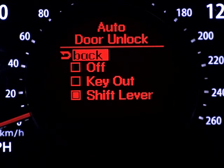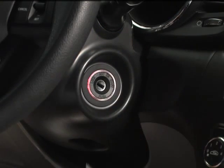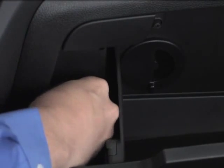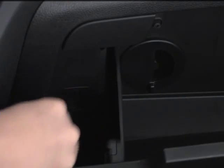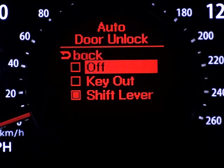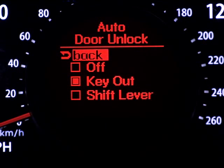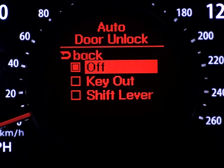Here you can choose to have the vehicle doors unlock when the key is removed from the ignition, or when the smart key is removed from the smart key holder, or whenever the shift lever is put into park. Use the trip button to highlight your preference and press Reset to select it. You can also choose to turn the Auto Door Unlock feature off from this screen. The doors will now unlock normally.